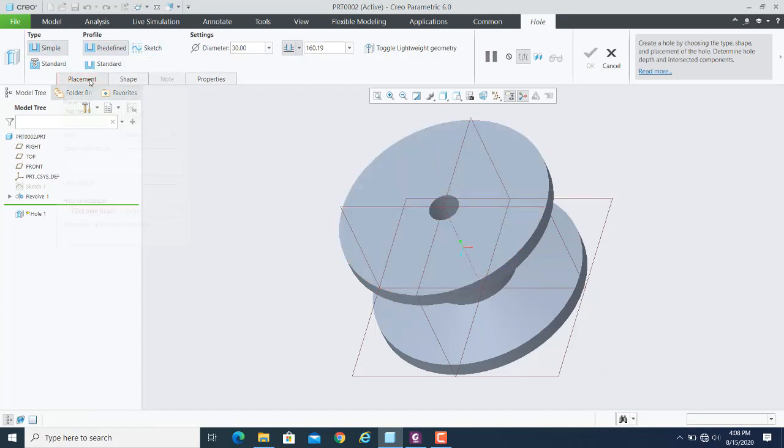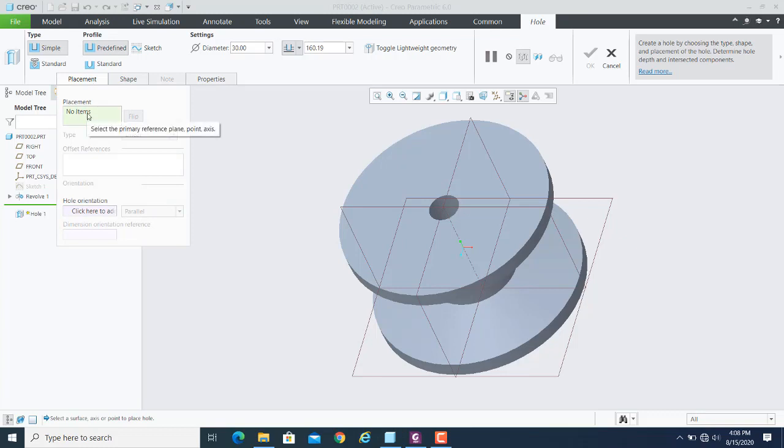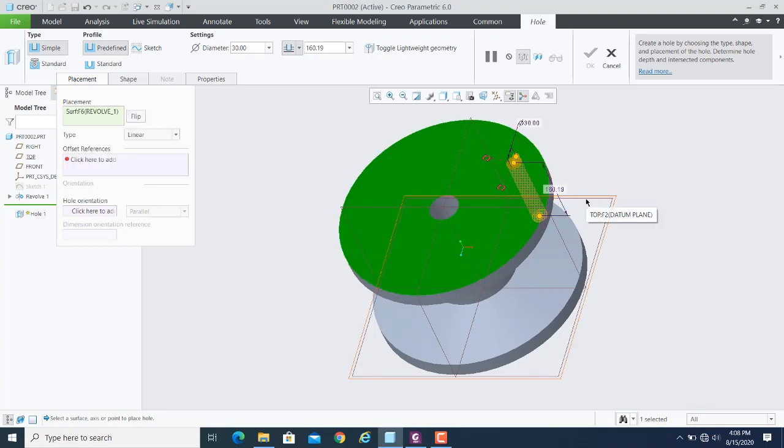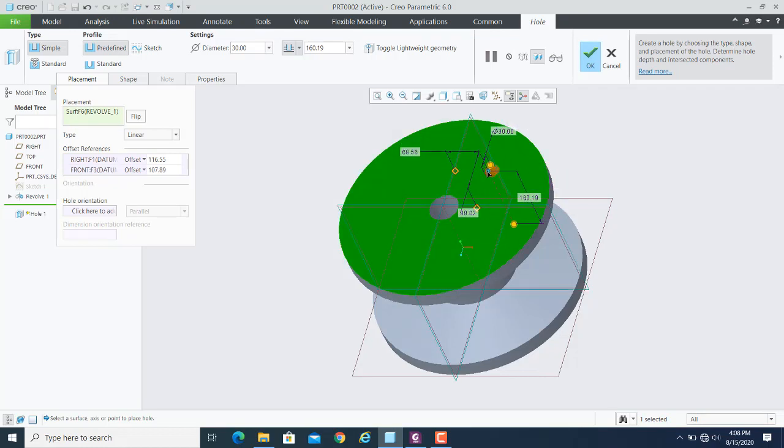it is simple. First you have to select the placement surface. For example, on this top plane face, if I want to create the hole, I can place it, and then these are those two grippers which you will be needing for the references. So I can reference this hole from this plane and from this plane. This is rectangular placement that we did in the previous video. If you have a planar surface, you can rectangularly place a hole feature by giving two references. One is for the horizontal alignment and one is for the vertical alignment.